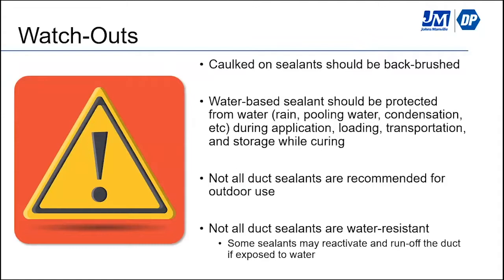At Design Polymerics, we use a product called styrene acrylic, and that's commonly used in roof coatings. We are well aware of the issues that water can cause on water-based duct sealants, even after it's cured, and we have addressed those issues.